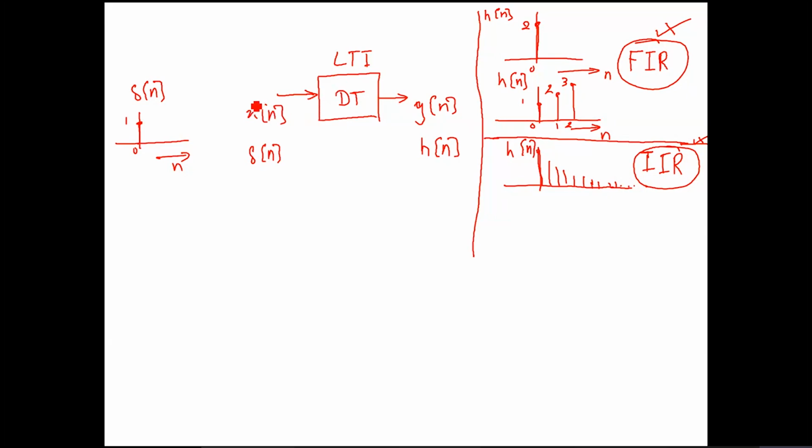But here, coming back to our original topic, that is the theory of convolution. For convolution theory, we first of all covered two basic concepts. One concept was that of an impulse response h of n. The other concept was that of breaking up x of n in terms of a sum of scaled delayed impulses. Okay, so coming back to this, if we have an LTI system, delta n, a single impulse, will give you h of n, the impulse response.